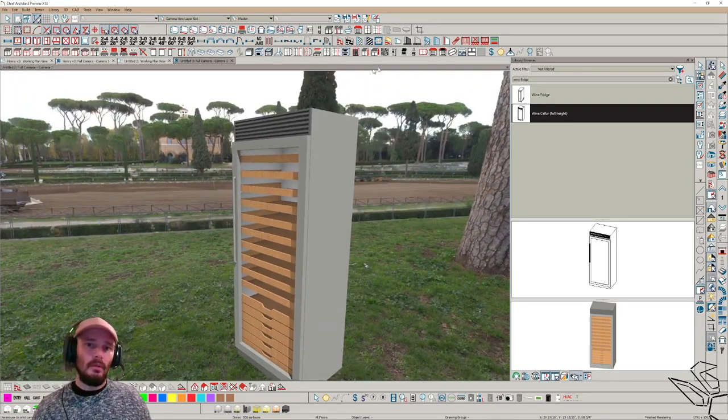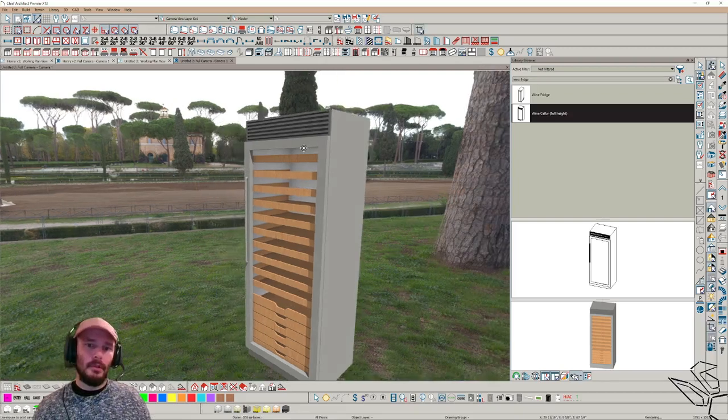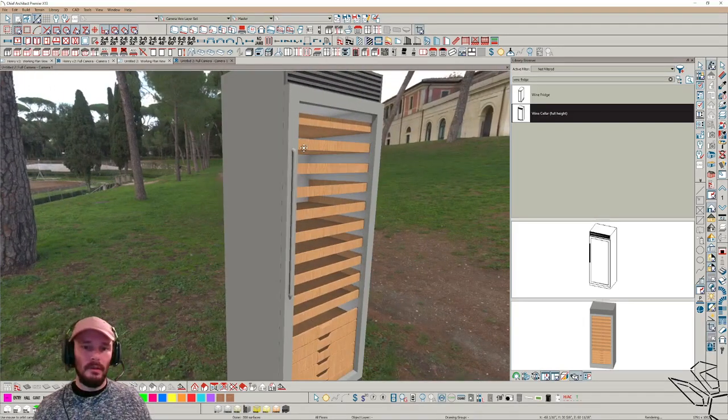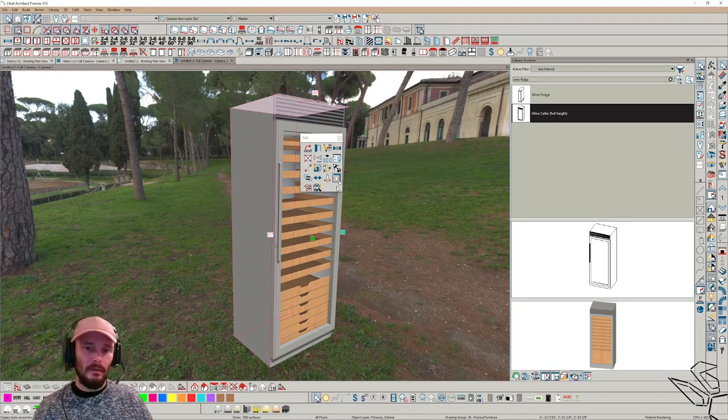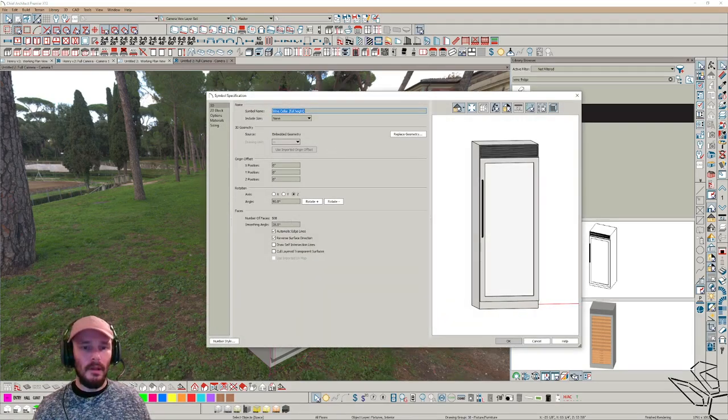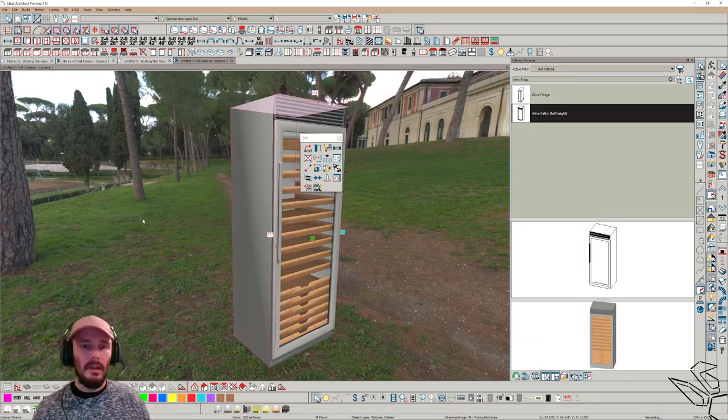And so I'm going to turn on perspective crop mode. That means I can get in real tight if I need to. And then I'm going to edit this symbol first. And I've talked about this before. I don't know how to relink to it, but let's just open the symbol up. And here's what I'm going to do. I'm going to pump this smoothing angle up to something like 140. It's going to make that really easy for me to delete certain parts of this.